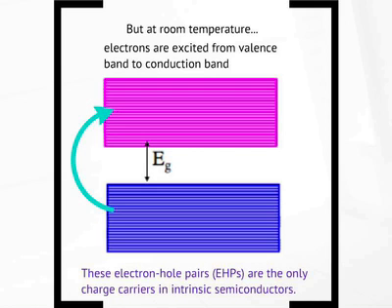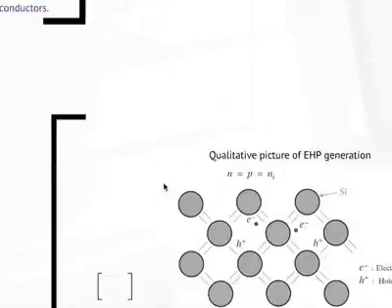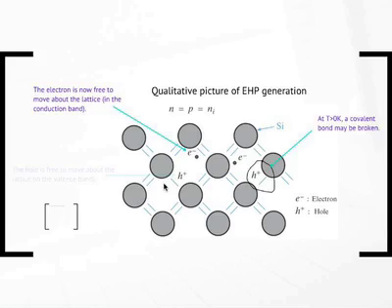But imagine a semiconductor which is in thermal equilibrium with the surroundings. So it's not gaining any energy, it's not losing any energy. Any electron which is excited up to the conduction band must also come down to the valence band at some rate. So you have a steady state distribution. So you have a steady state concentration of electrons here, steady state concentration of holes here. Okay? That's what we're talking about.